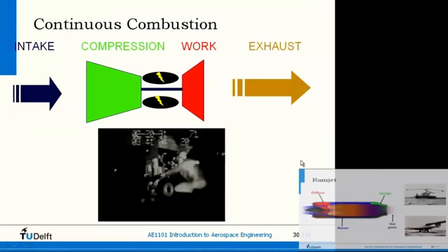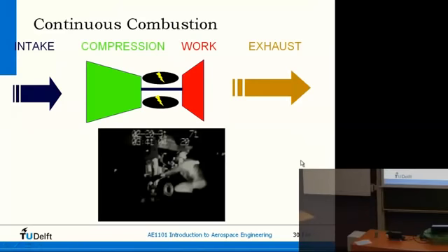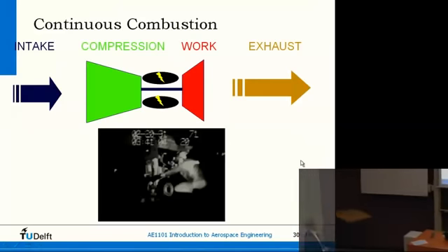I think one of you rightly asked, how do you start it? Well, you cannot start it without some external help. So, for instance, indeed, the APU could provide the electricity, but otherwise an external electric generator has to start the turbine before they can actually get it running. Well, with the ramjet, it's even worse. You really need quite some speed to get this going.